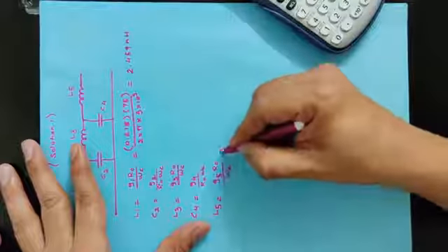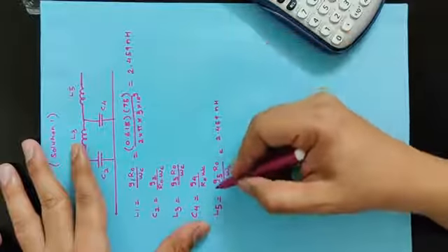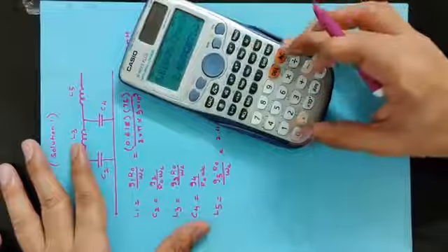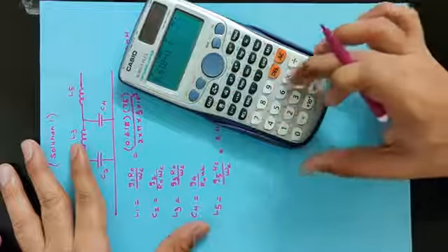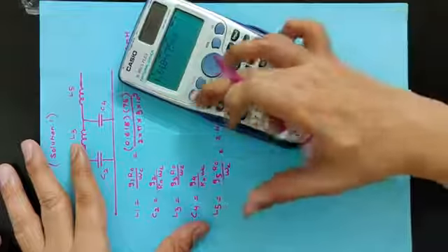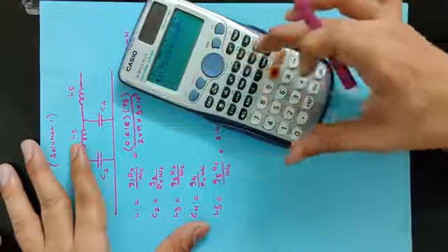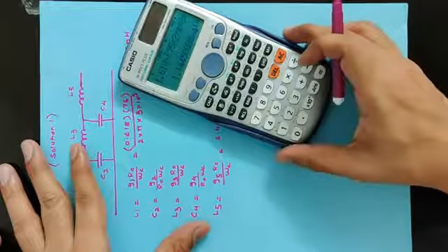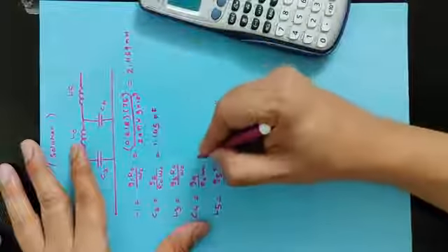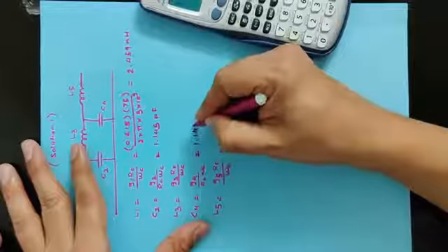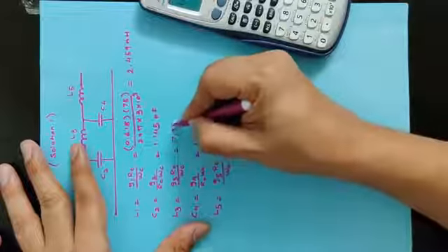This value will be again the same for L5. C2 and C4 we will calculate. So C2 will be G2, that is 1.618, divided by 75 into omega c, that is 2 into pi into fc, which is 3 into 10 to the power 9. So it turns out to be 1.145 picofarad, and the L3 value turns out to be 7.957 nanohenry.